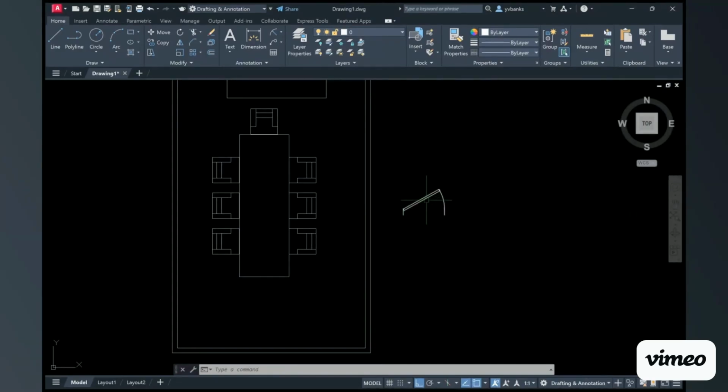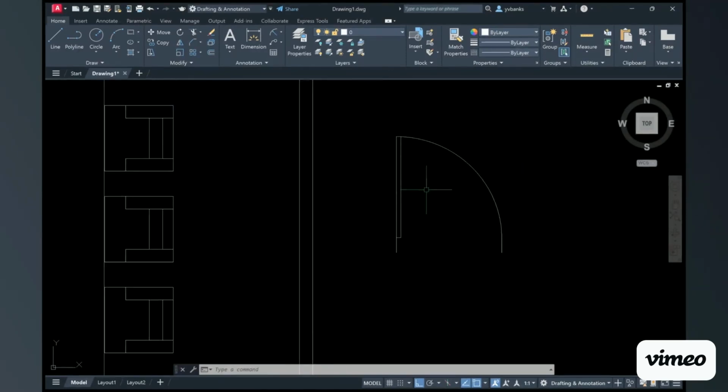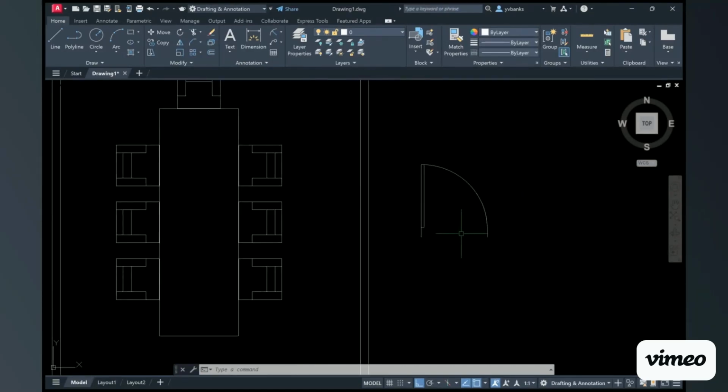It is a default size of 3 feet. I can use these arrows. The arrow here helps me with the opening. I can open it, and I'm going to suggest we open our door for now at 90 degrees. And now we have a 90-degree angled door. This rectangular vertical shape is the actual door slab, and of course the arc is just showing the direction of the swing.